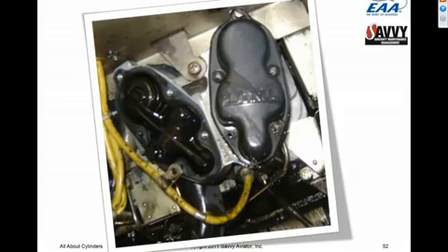Of course, when the rocker cover departed, all the oil followed it, and the engine had a catastrophic lubrication failure through the number 2 rod, through the top of the case, knocked one of the magnetos off, and the engine was complete scrap metal. The owner did an amazing job of dead stick landing this airplane. But this was clearly a mechanic-induced failure, as was the last one.